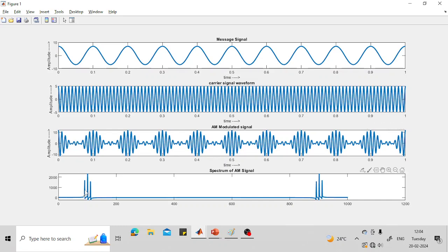But you see here, the sideband amplitude is crossing half, more than half, because the modulation index is more. See here, 1696 it is. And what about this one? It is 2346, means it's more than half, right? That's the reason. This is how the spectrum is changing for different modulation index, and also the time domain signal is changing for different modulation index.